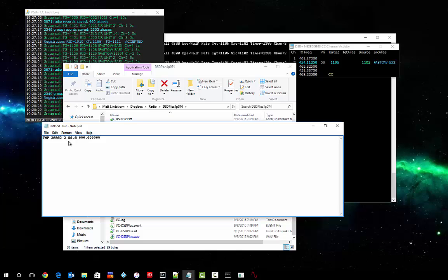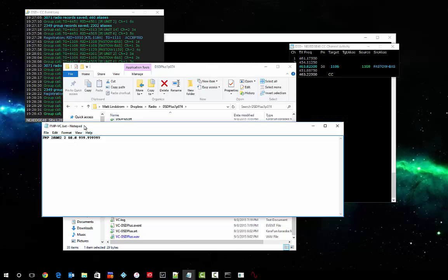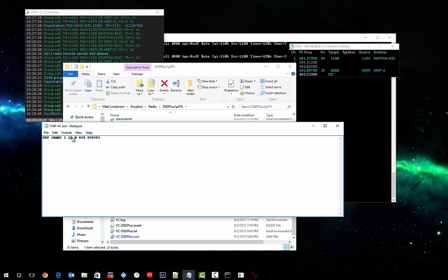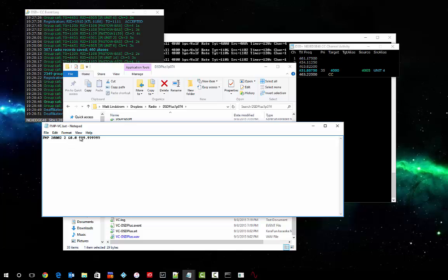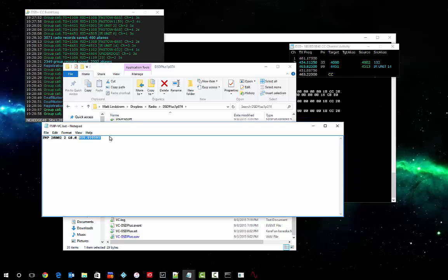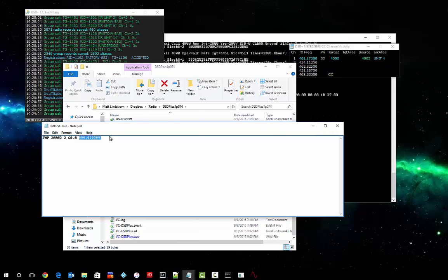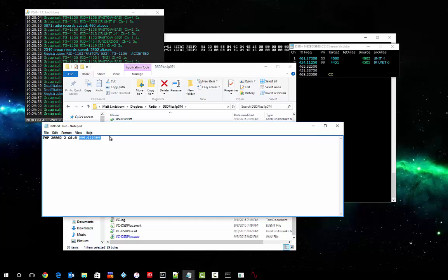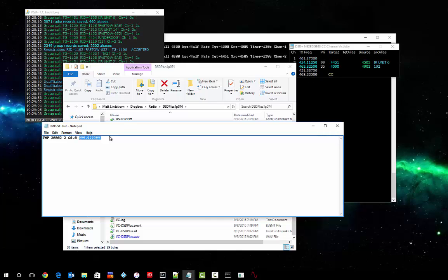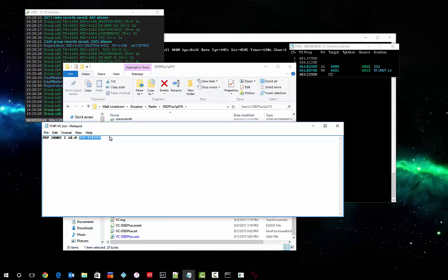Okay, I already used my first RTL device on the control channel, so I'm using device 2. The plus 88, plus 87 was the other dongle, so I'm going to put this one down to 68. Now, there was a feature introduced with this, of course, to actually follow the voice, and there was a button that the manual says that you have to hit to enable the voice following, and you would normally run this and hit the V key on your keyboard, and it would go into the voice following mode.